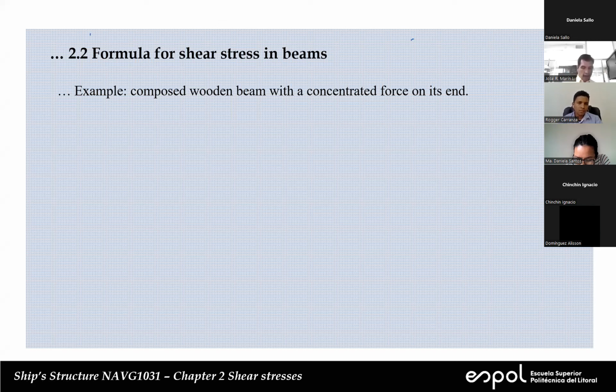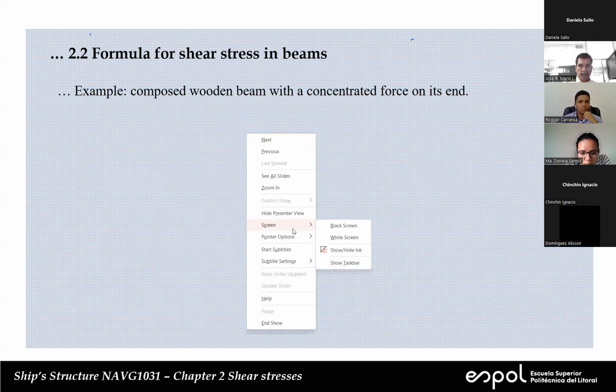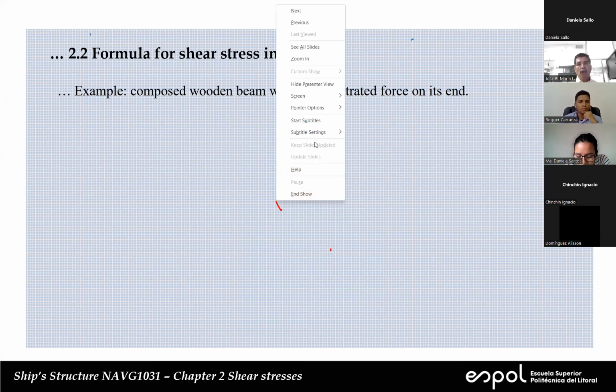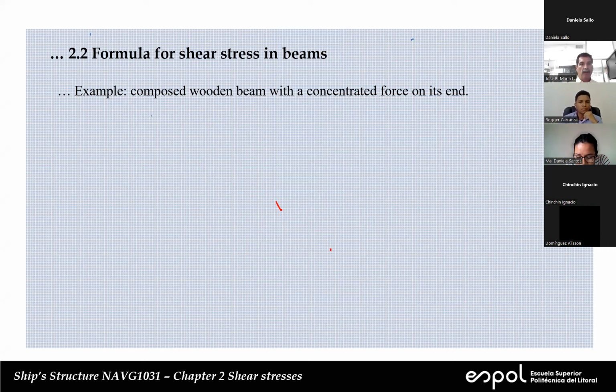Yes, doctor. Okay. See, what's the problem with a section, for example, a ship section, which has a longitudinal bulkhead? That's quite common, right? The problem is that there is no point where we know the value of the shear stress. That's the problem. Okay, so let's consider a simple section like this. It's a barge, and we use a single bulkhead.